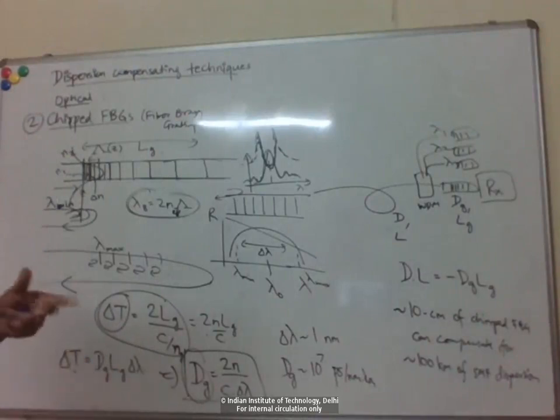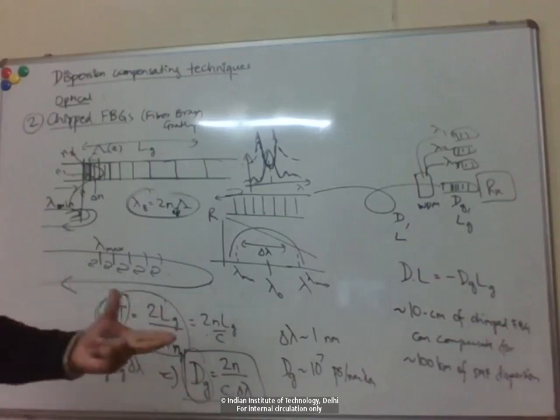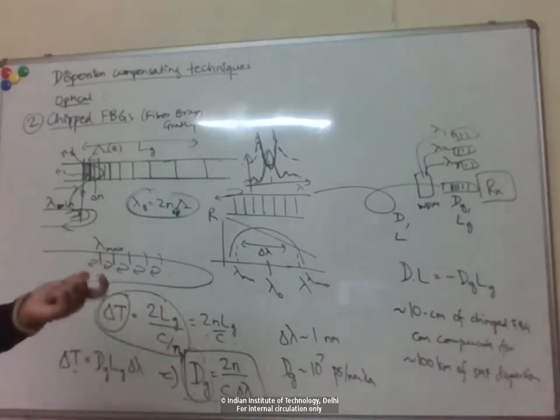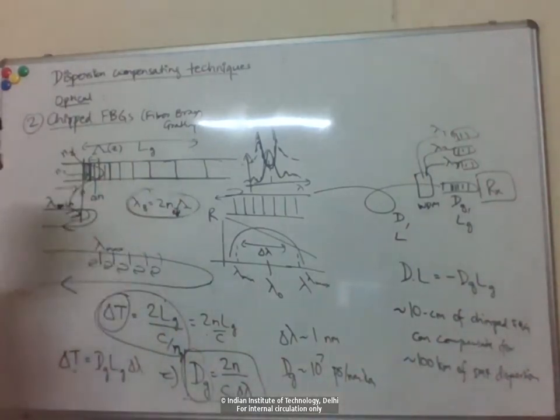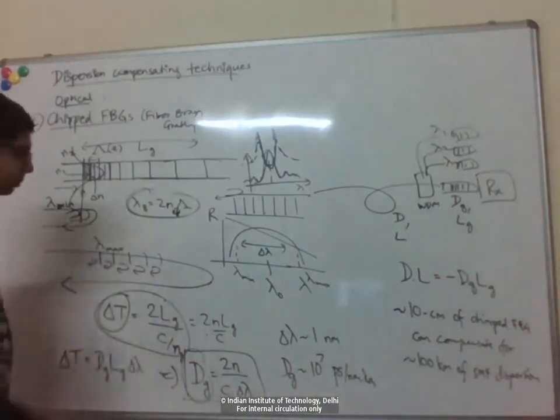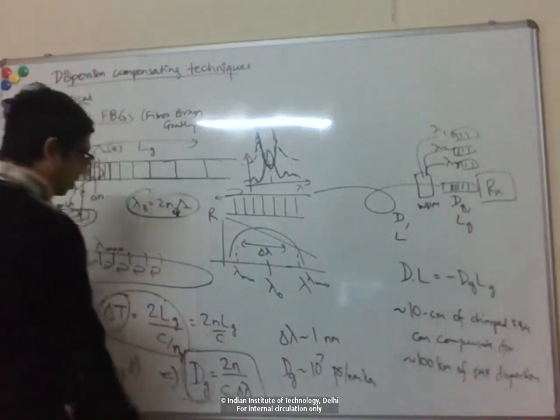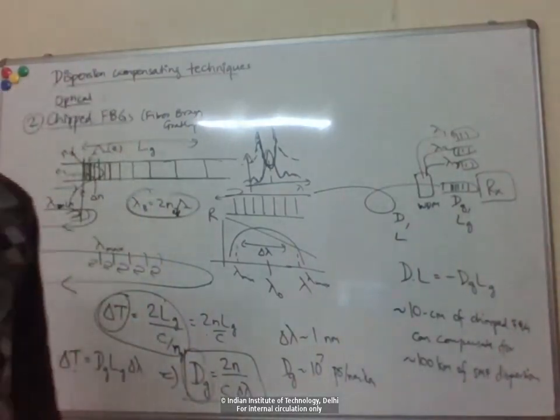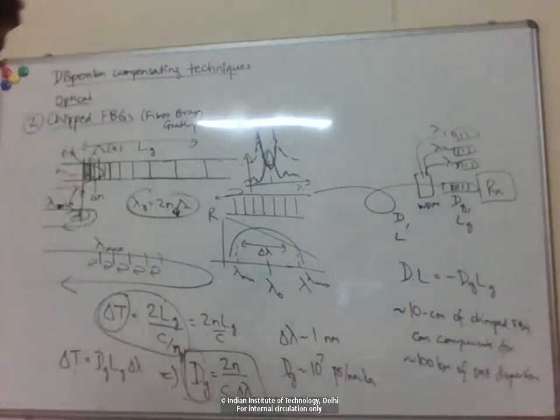In the coherent source case, you get this chirping effect, and the pulse width of the data rate itself determines the broadening. But in both cases you can use these techniques because you're compensating for the fiber dispersion itself.